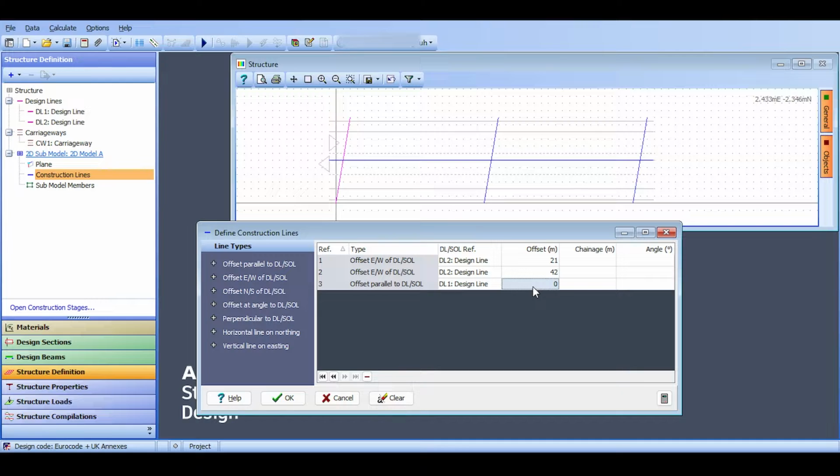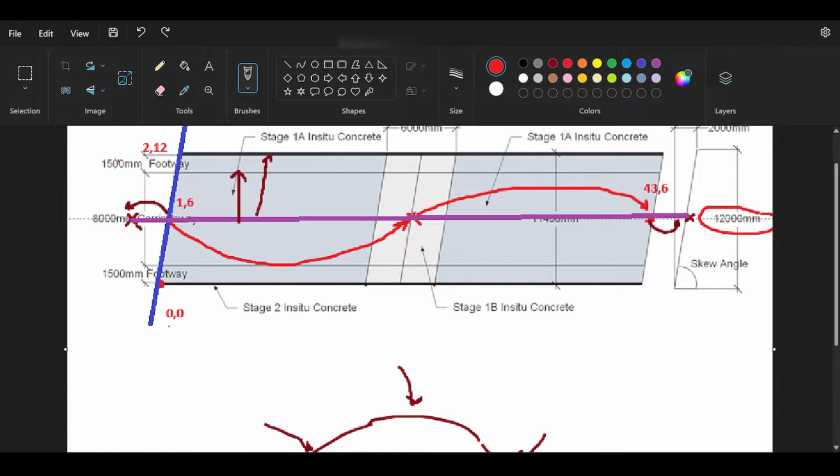You would think, wait a minute, why 5.6 and negative 5.6? Because I know that this is the footway. The footway is at 5.5 meters away, but because there's a finite element that we will add here later, I will add 5.6. So this is the center line of the finite element I will be adding later.